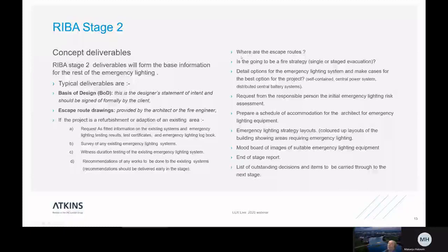Right, so fire strategy. There may be a fire strategy, but in small buildings there may not. It may be that the architect is the fire engineer and he's just going to provide things there. But if you're talking about a fire engineered building, you need to talk to the fire engineer and understand what the fire strategy actually is and how your emergency lighting works alongside it.